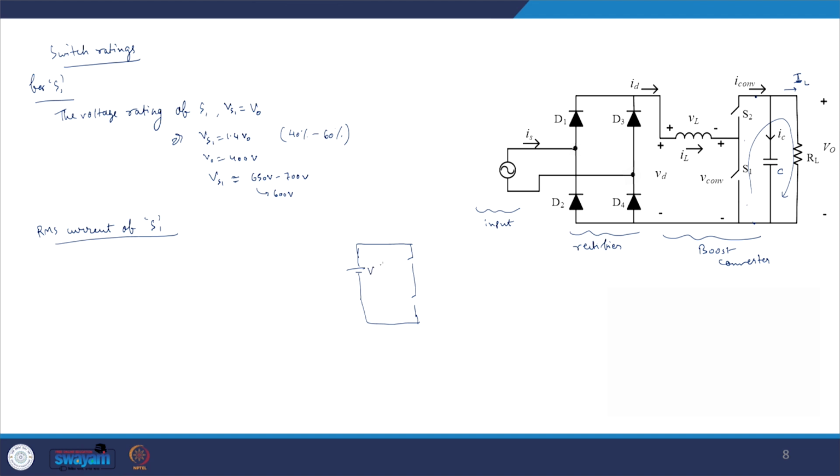We have VDC applied across this half bridge, and at the output of the half bridge we assume a constant current being drawn. This is a common architecture in voltage source converters, where the inductor is kept at the pole of the half bridge.